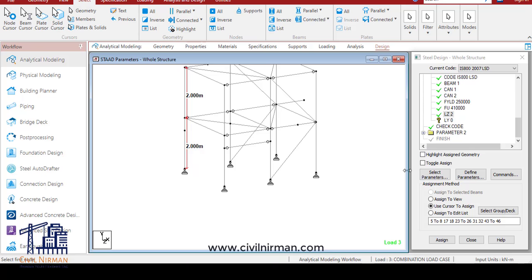Now let's talk about minor axis. Even though we have a beam at 1.5 meter, can I break Ly as 1.5 meter for this length? No, I cannot. As I explained earlier, since there is no brace, whenever the force comes, this entire frame or this particular column will move in spite of the beam being there, as there is no brace nor is this a rigid connection. So we can skip this length and move on to the next height.